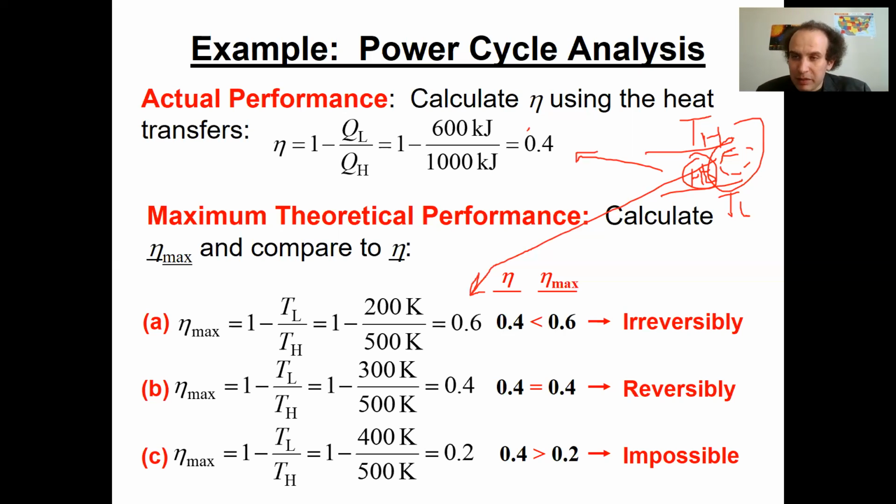If Carnot efficiency will be the same 50%, what can you say? You say, I will not invest money in this because it's an idealized cycle, but you cannot decline it. Potentially this may happen. But if maximal efficiency is 45%, then you say, I don't want to read it, it's garbage. Remove it because it violates the second law. Something is wrong there, I don't care why. It's wrong. Do you understand this point? That's the analysis you do.